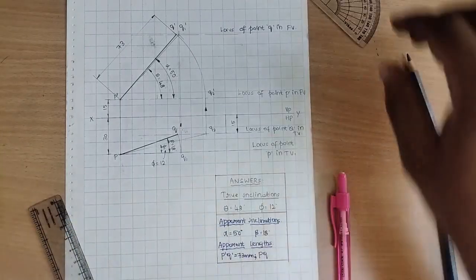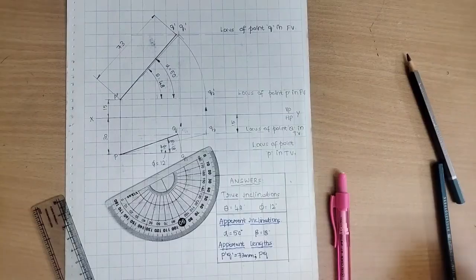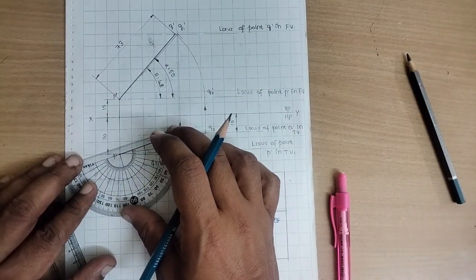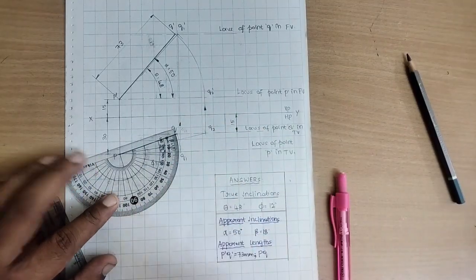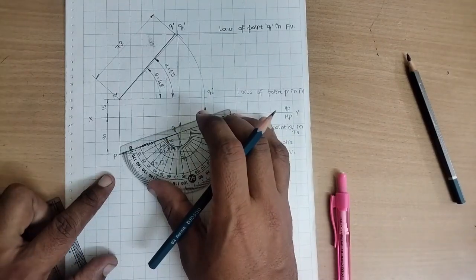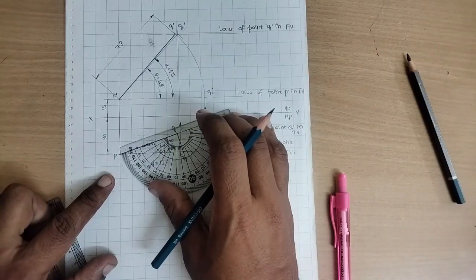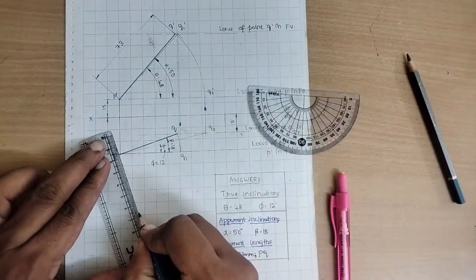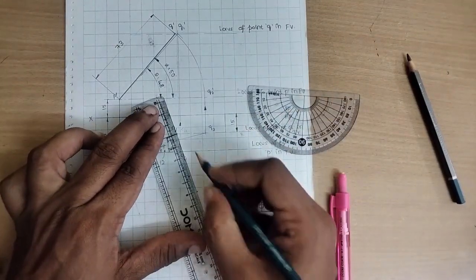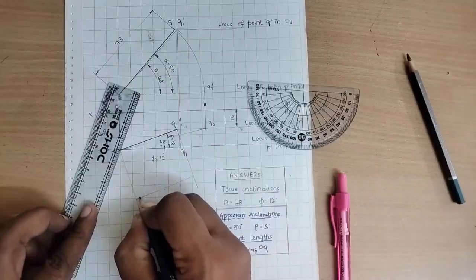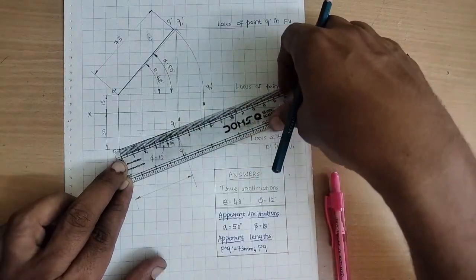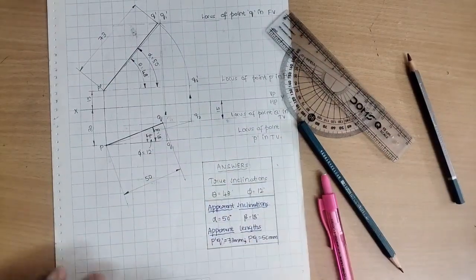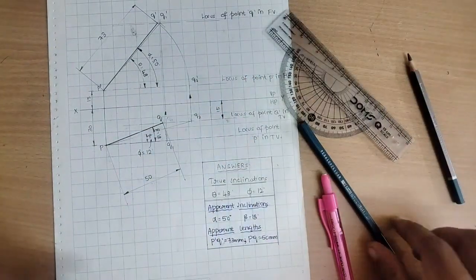Similarly, what is PQ? Let us go towards the bottom of the sheet since we have plenty of sheet available. With P as the center, 0 degree in par with the apparent length, mark 90 degrees here. Similarly, with Q as the reference point, place a protractor on the point Q. 0 degree should be on PQ. Mark this as 90 degrees. Draw one 90 degree line and one more 90 degree line. This is 50 mm. We need not measure this one, because this is part of the data. And true length we need not find out, because it is already given in the data.